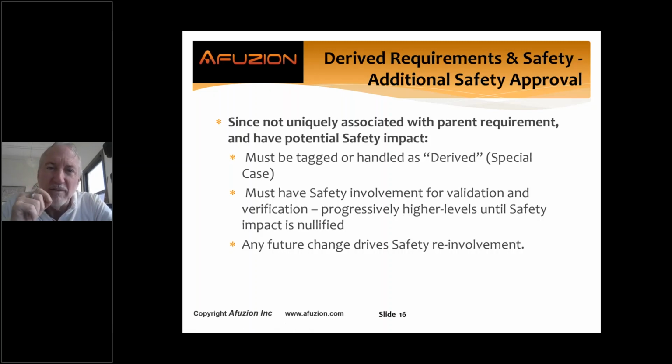It might be unsafe. 178C explicitly says so, 254 does not. 178 explicitly says all derived requirements must be fed back to the system process until the safety is affirmed, okay? Well, 254 doesn't say that, because 254 is old, but we use the same process, the same ecosystem, okay? So it is required to also do that for hardware-derived requirements. That's the process. Prove that safety has reviewed it via systems, and it's safe.